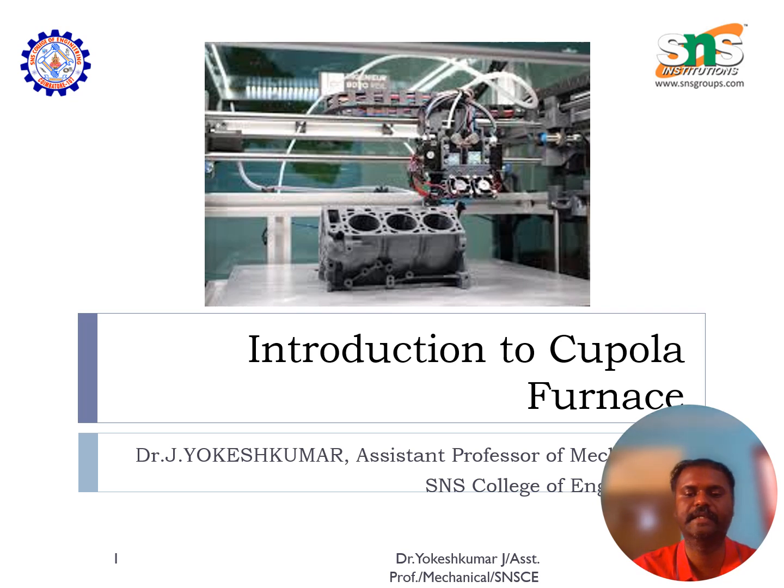So we know that melting is the phase change process where we can change the phase of any metal into a liquid state. We know that foundry is the process of producing a metal part by creating a mold using a pattern and finally melting a raw material and pouring it into a mold cavity. Finally, the solidified part is known as casting. So for doing the melting operation, we need a furnace.